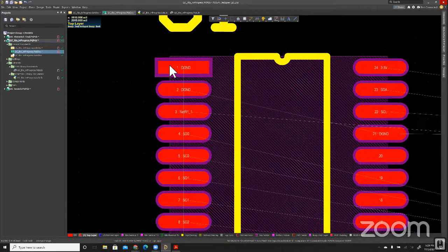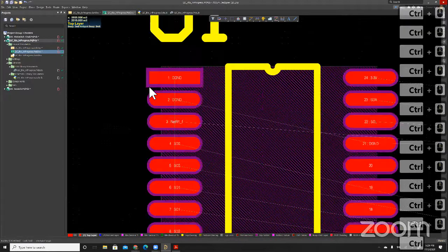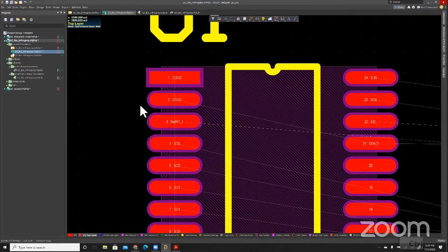So if you don't have too much solder, you can use the heat to flow it over, and then if you've got a gap between your mask, that helps prevent the bridges there. So the wizard that I used actually made the solder mask so big that I had to go and modify the pins to reduce the solder mask a little bit and have a gap between there.